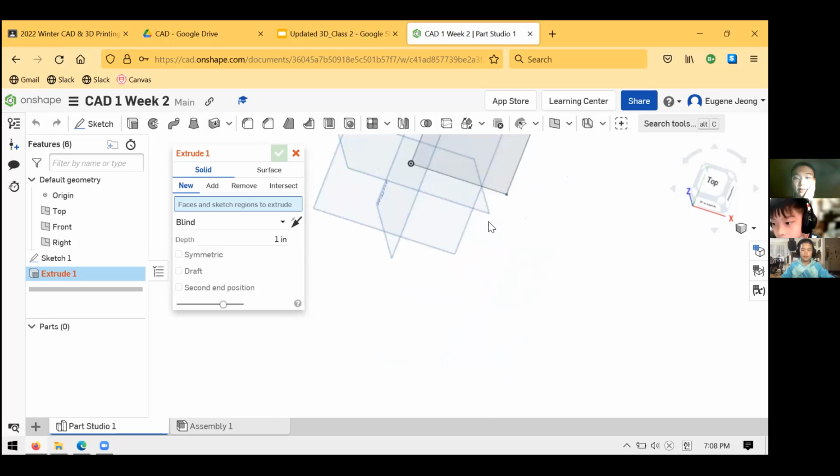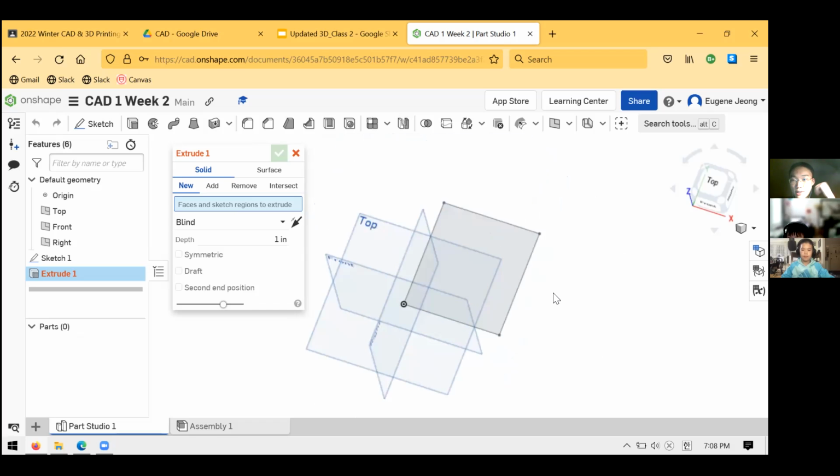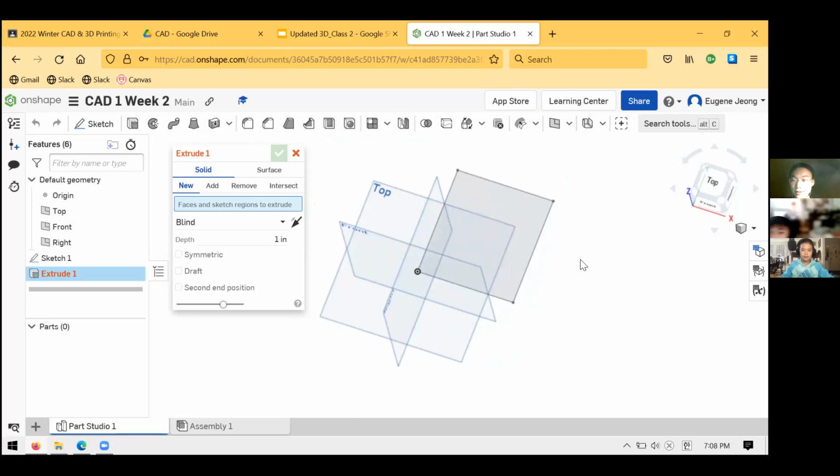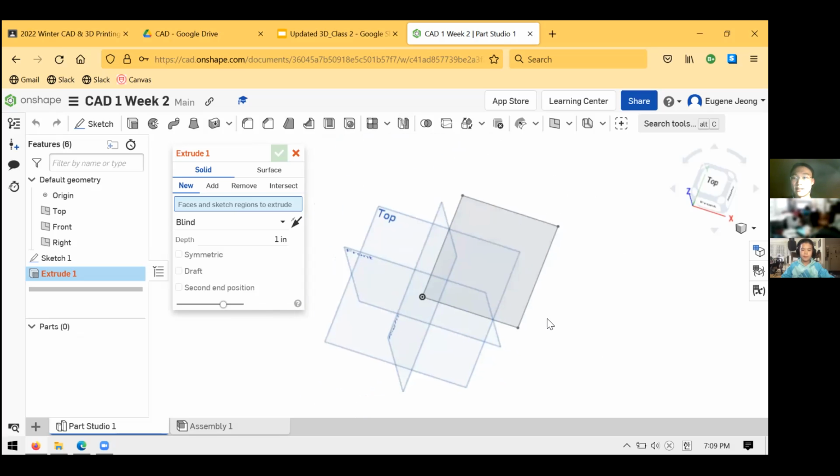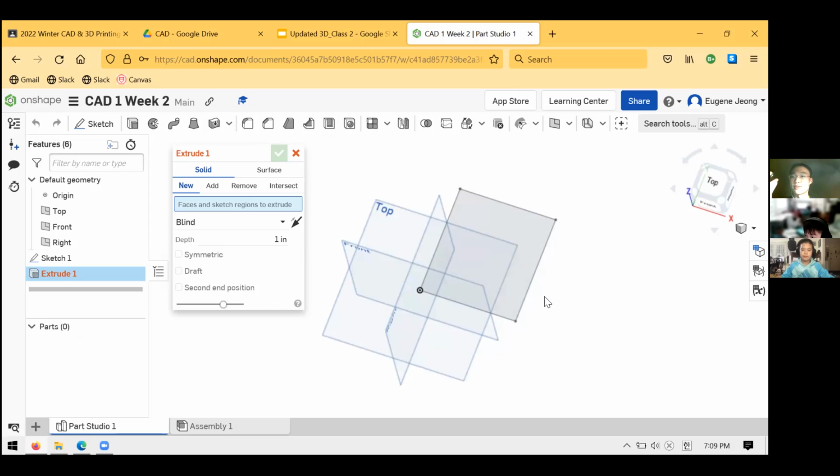So right now you're looking at it like this. If you middle mouse and just drag down, it'll bring everything down a bit. And hopefully that works. I believe there's an alternative command you can use. Yeah, the alternative, if you for some reason don't have a middle mouse, is control right click. If you hold control, then also hold right click, then move your mouse around. That does the same thing. So if your mouse doesn't have an M3, then you can just do that.